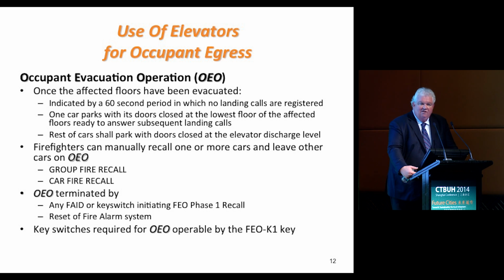And occupant evacuation operation will be terminated if there's a reset of the fire alarm system or any smoke detector, any fire alarm initiating device or key switch is initiated or activated, which would normally initiate firefighters' emergency operation phase 1 recall. And all of the keys have to be the same for both systems, for OEO and FEO.